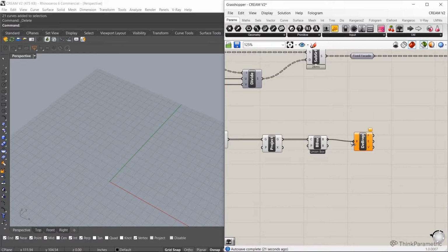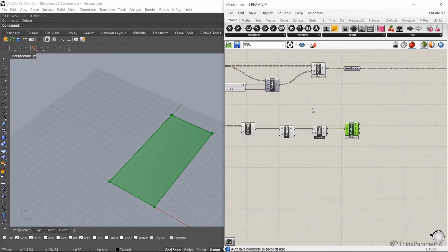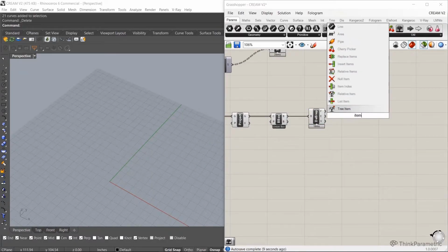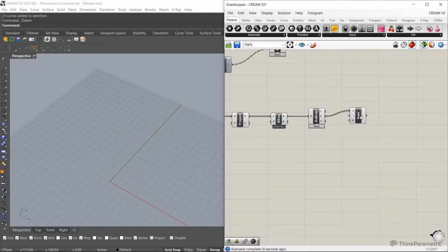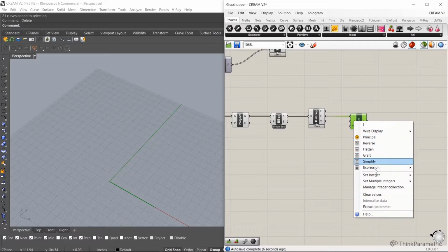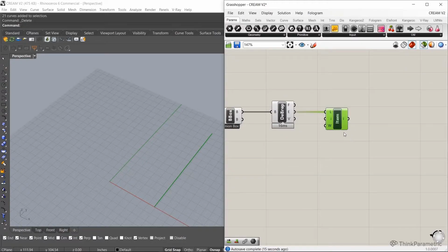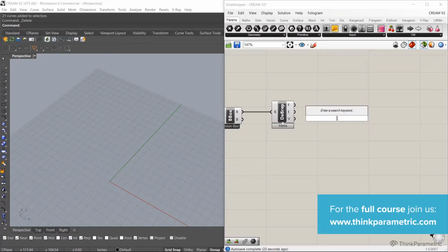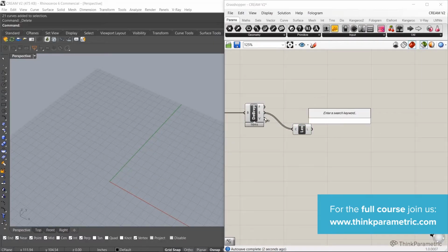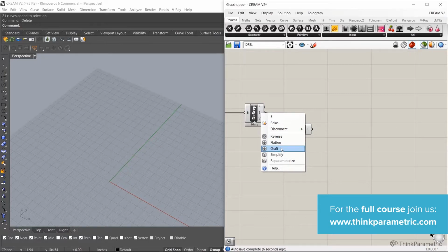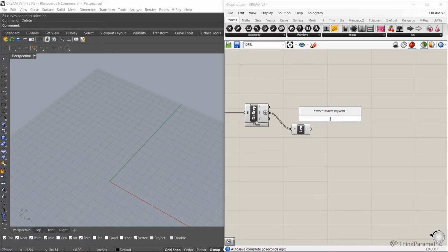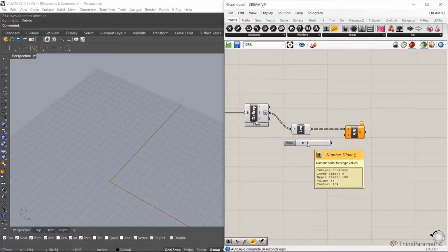So we're going to grab this. Let's see if we can deconstruct BREP. So we can grab our edges. In this case, we can grab, depending how it's ordered, this is our long face. And in fact, we can just go grab the length of our edges. And then we'll graft these. Let's divide that by a fixed number. Let's say our optimized panel, or like our nominal width for our panel, is 15 feet.